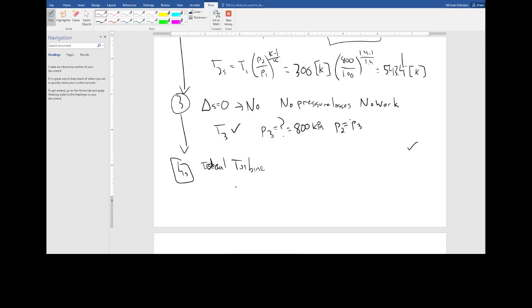And I didn't do this for the compressor, but suppose I show you why it's isentropic, right? So if I did my second law analysis, dS/dt is equal to Q dot over temperature plus the sum of m dot in s in minus the sum of m dot out s out plus sigma dot, right? So here it's at steady state. It's adiabatic. It's one inlet and one outlet, and it's ideal.